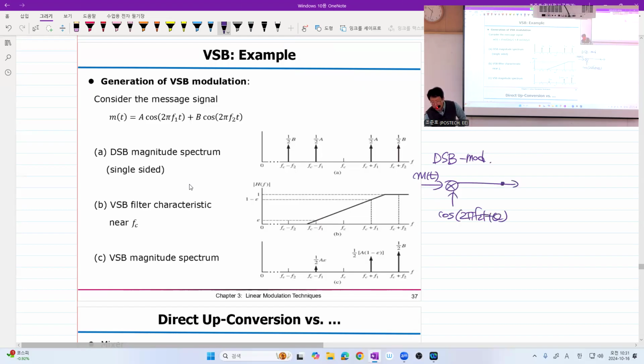You know that this signal has spectral efficiency of only 1/2, and in the frequency domain it looks something like this. Now, sideband filtering for SSB wants to filter this signal very sharply, but that is not implementable cost efficiently. So what about filtering that way?